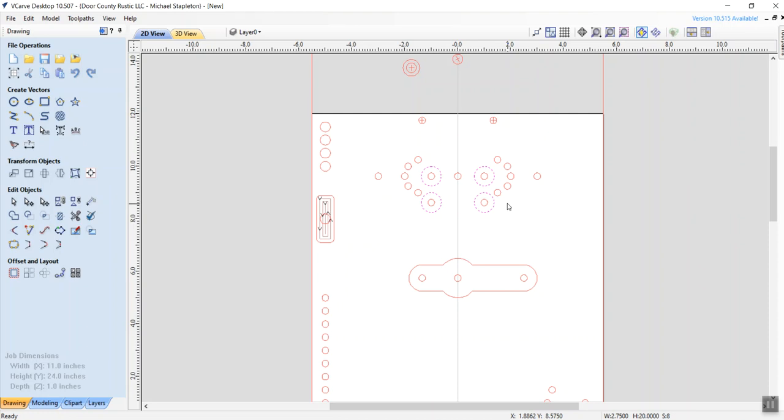And those of you that are into Vcarve, you know that I could have done this a little different. I could have done these first because they're going to go down. Let's take them down 0.375 because then after we put a bolt in there or a GRK, if somebody wanted to, they could put in a 3/4 inch plug. You need a little space for that. But going back to that, I could have done these first, and then when I go to the insides, I could tell those inside ones to start at 0.375 and then only go the remaining 0.625. Well, it's not worth all that time of trying to do that on a couple of small holes like that.